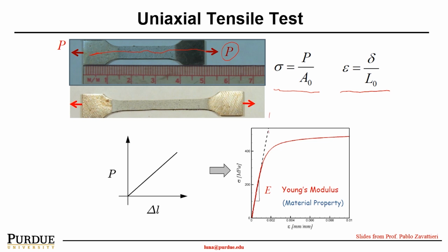First is the linear deformation area, which is about 0.2% of the strain in general. As shown here, when the material has around 0.2% strain, we can see a very linear behavior of the material.